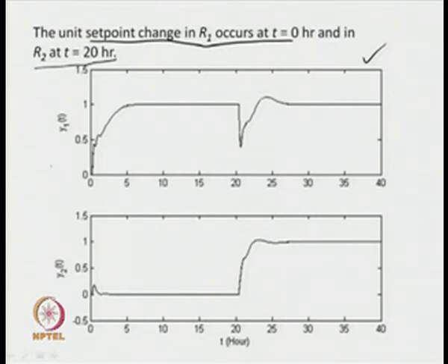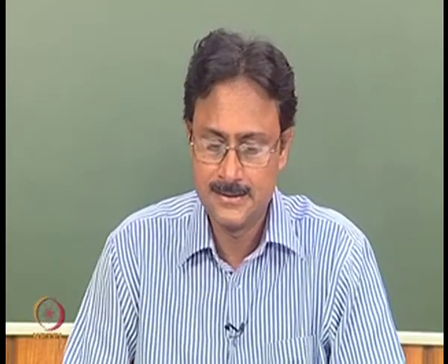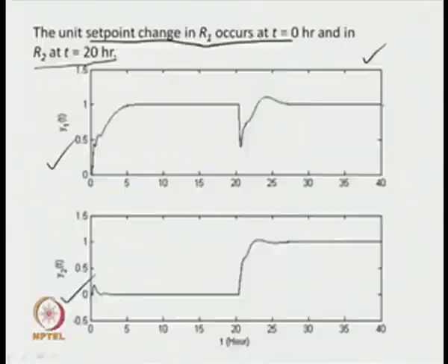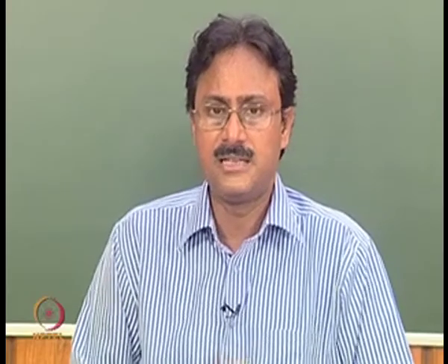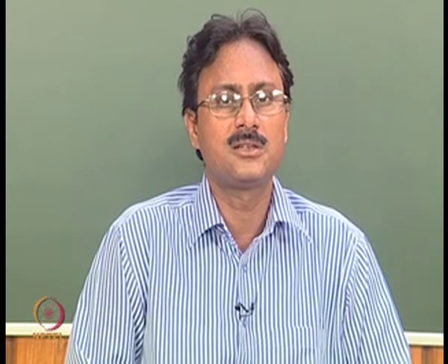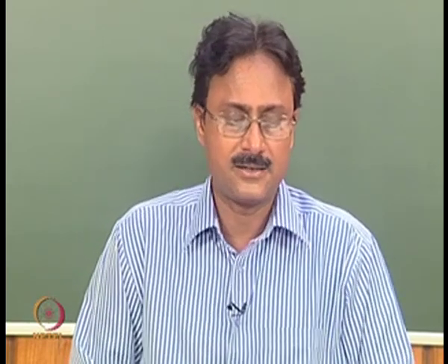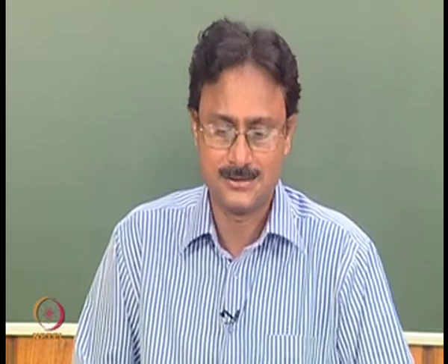The upper loop response is given here and the second loop is giving a time response of this form. The responses show acceptable settling time, overshoot and speed of response. So, we have quite satisfactory overall responses, improved performances from the PID-P scheme. So, splitting the P control helps us in obtaining satisfactory performance of the TITO system.